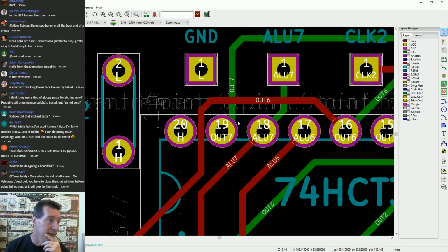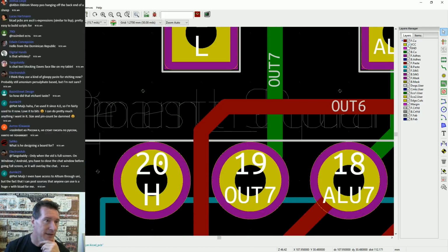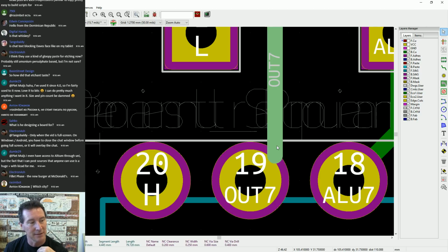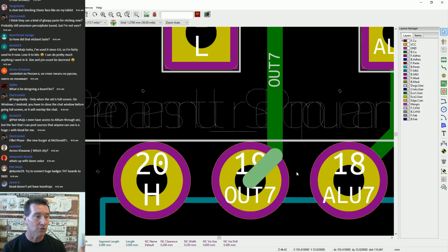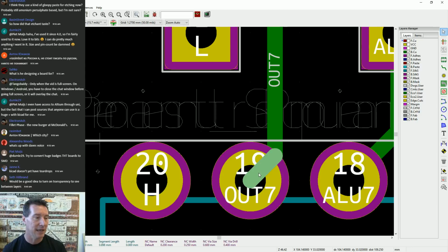Now that we're talking about this, see the problem here is this trace coming down. This is not good layout. You don't have your trace coming down at an angle, even though it might be angling in properly and physically connected. Oh yeah, look, that's really bad. Oh no, there it is, it's hidden. So it's going to the center, which is all great, but then you've created the acid trap in there. It's just not good design technique.